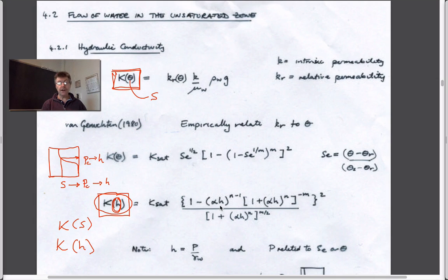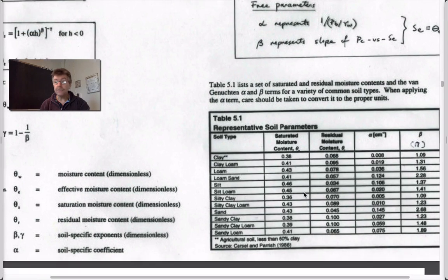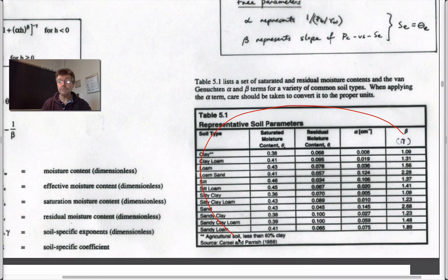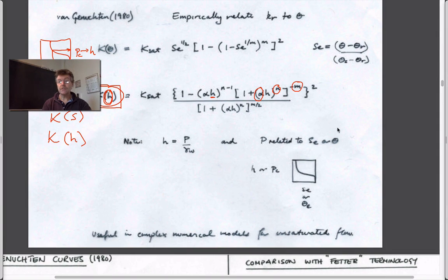And so if you know what the hydraulic head is in your aquifer, and if you know the values of these parameters alpha, n, and m, which by the way you can get for different materials, which are just shown here, then immediately you can construct the relative perm curves that we think are so elusive to us, to be able to determine the behavior of Kr versus volumetric moisture content.